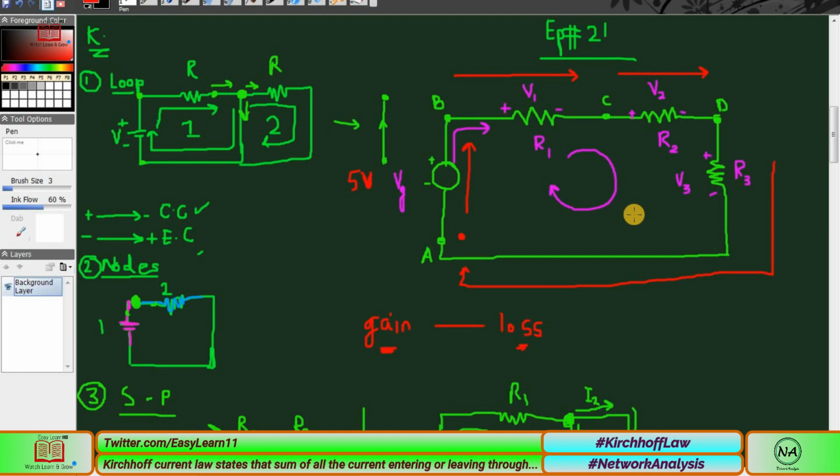Okay, now coming back to what I am discussing, we need to define some voltage law, starting with node A. Now let's start. We have a node A here. We assign a positive sign to the voltage if the polarity marks occur in the order positive to negative. Let's say this is our starting point, and we will assign the positive sign to all those elements. This is what I decided as a reference. This is up to me. I can decide whatever I want.